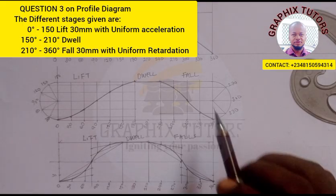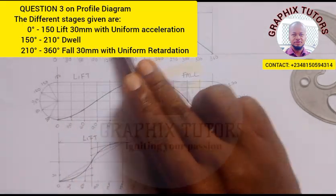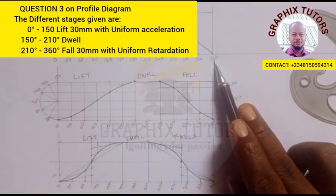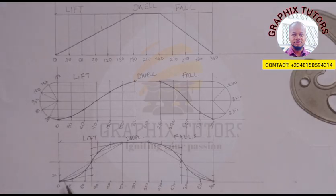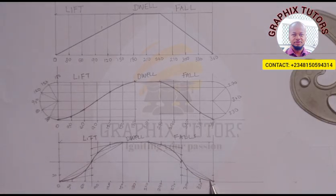So the uniform velocity: rise, dwell, and this is fall. So it's rise with uniform velocity and fall with uniform velocity. This one rises with harmonic motion and falls with harmonic motion. This one rises with uniform acceleration and falls with uniform deceleration or retardation.